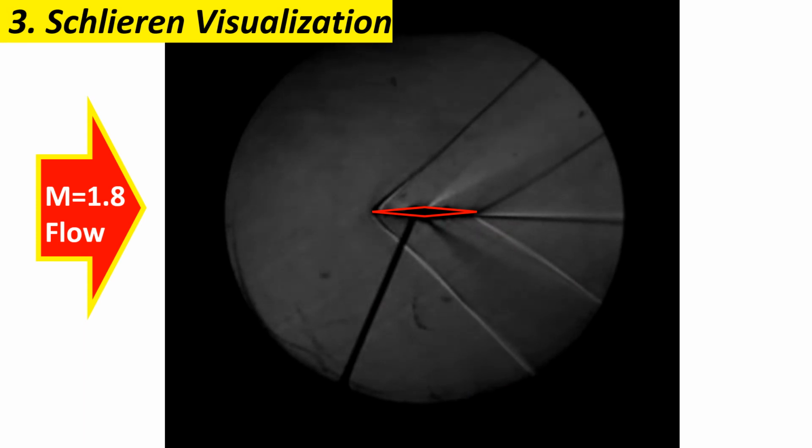Okay, so this is a steady flow we are looking at, and we have the leading shockwaves, expansion fan, and also the shockwaves at the trailing edge, and also the wake of the flow. So this is what you can expect in the wind tunnel. Just to mention, the angle of attack now is 0 degrees. So there's no angle of attack.